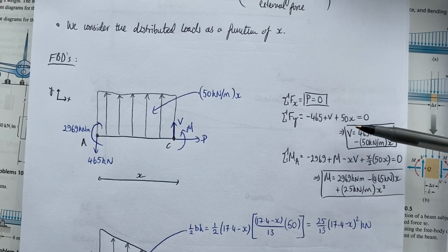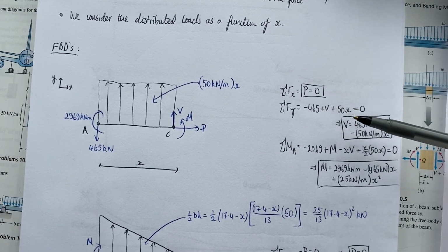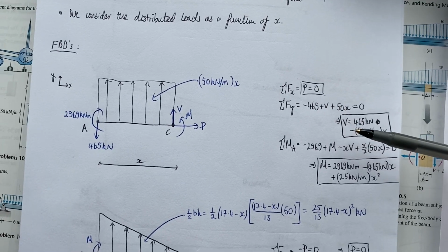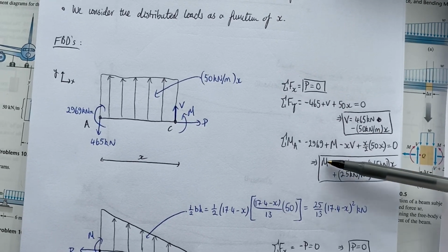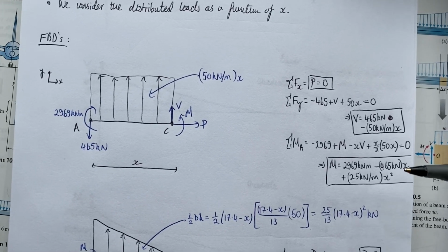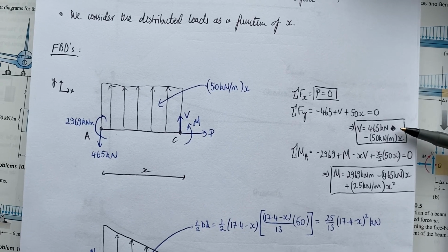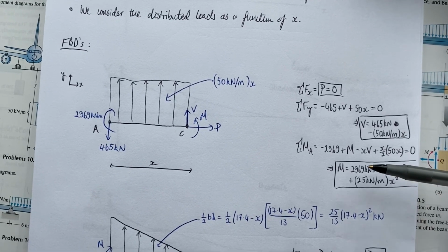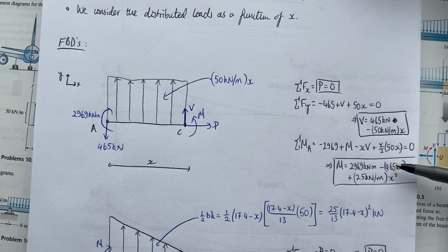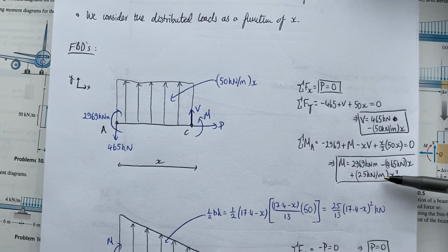So make sure you can replicate what I've done there with finding the axial force. Well, that one's easy, but the shear force and the bending moment. Now, just to point out at this stage, I have this function here, which is a linear function of x, and then I have this function, which is a quadratic, right? So immediately I can see that I'm going to have to draw some curves this time.